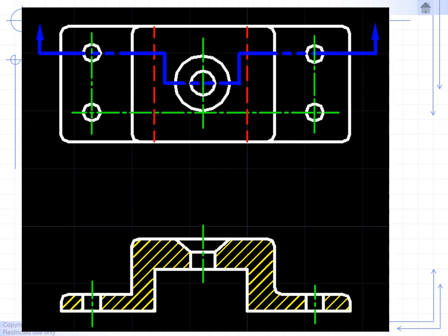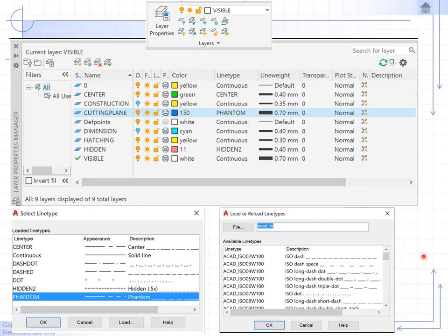Next slide. So you're going to have to set up your own layers from scratch, since you're starting the AutoCAD file from scratch for this chapter, sectioning in AutoCAD. Or unless you use one of your old AutoCAD drawings that already have some of the layers set up, just open that file and save as with the new part number or file name. Okay, let's say you're setting up your own layers. So you go to the layers panel up in AutoCAD above, click on the layer properties, and the layer properties window will pop up.